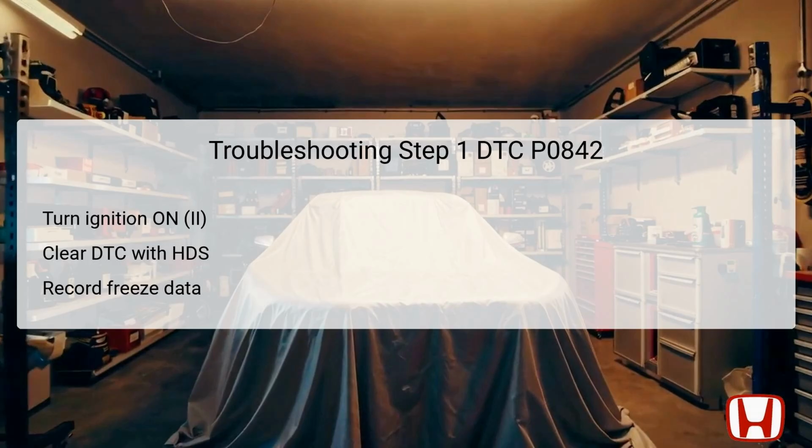It's always good practice to record all freeze data prior to clearing the codes, as this data may reveal historical information about the conditions present when the trouble code was triggered. This initial step sets the stage for further identification of the current status and alerts the technician to the nature of any ongoing issues. Accurate recording of information will assist in making informed decisions in subsequent troubleshooting steps.